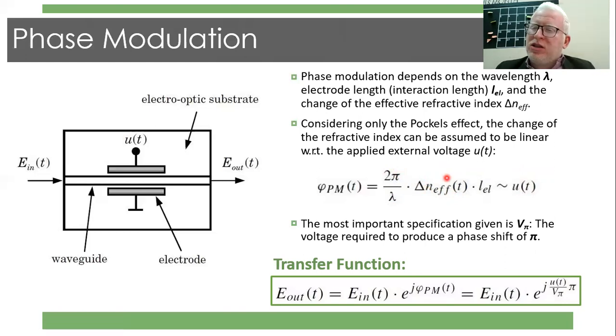Accordingly, my dear students, if u(t) is your message, you can now include the message in your laser by inserting this message terminal onto the electrical field electrodes. Accordingly, any variation in the message will be reflected in the refractive index and automatically will be reflected in the phase change of the laser, or the laser phase change or polarization.